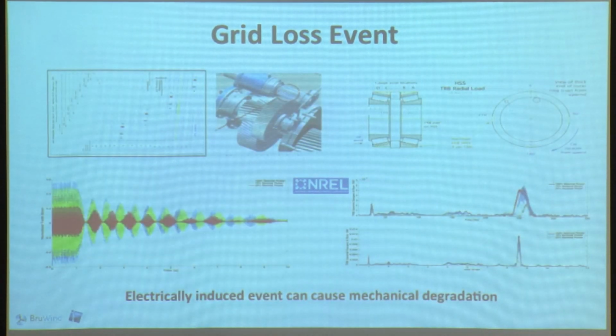So you get very strange behavior. And what we see is, we measure with strain gauges in the teeth of the gears. We see that while they are rotating, they start slamming. So one side, the other side, one side, the other side, but it's continuously happening while they are rotating. The frequency of slamming is driven by the resonance of the drivetrain. So it's a resonance phenomenon that you can predict because you can estimate the resonance. And this slamming is really impacting the teeth. That's still okay, they are very strong.